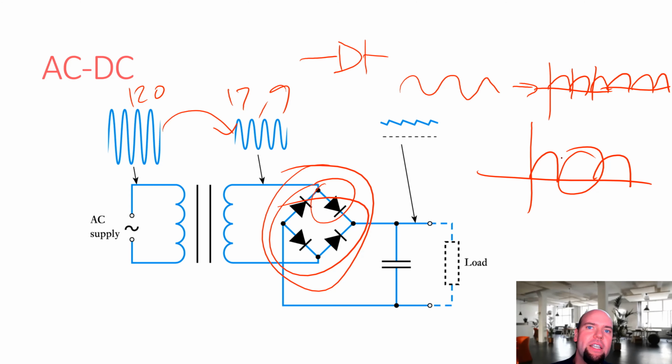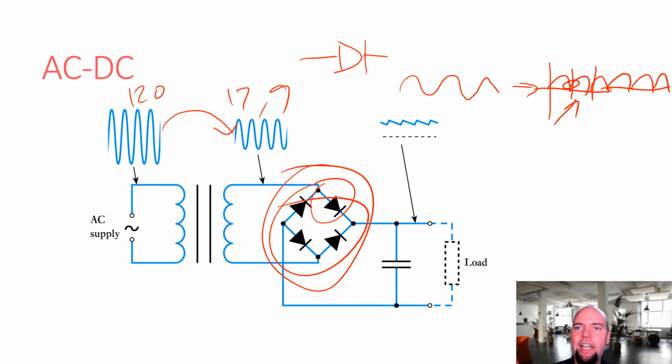And what does that mean? That means you're going to have to pay for some sort of energy storage device, be it an inductor or a capacitor, to store energy to keep providing it to your circuit in these little dead zones. Much better to do a full wave rectifier where you just have these tiny little dips. Much cheaper capacitor, much cheaper inductor, whatever you need to store energy, much cheaper. And then they're just using a capacitor here.